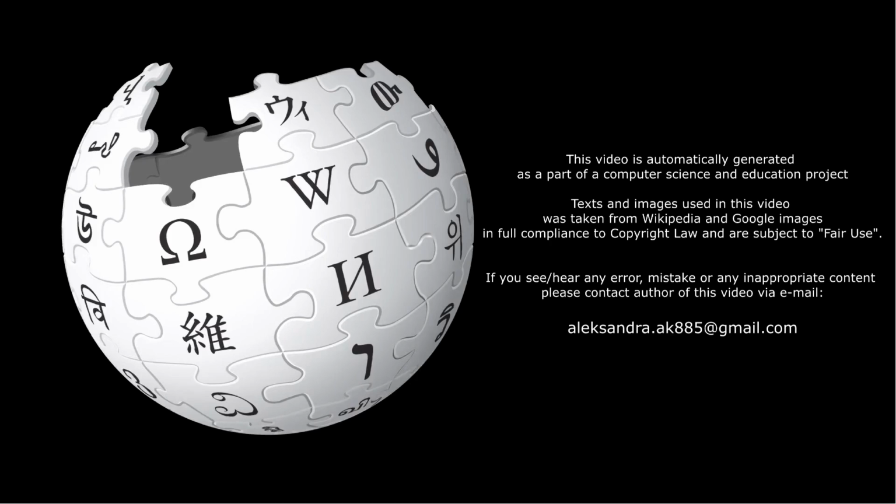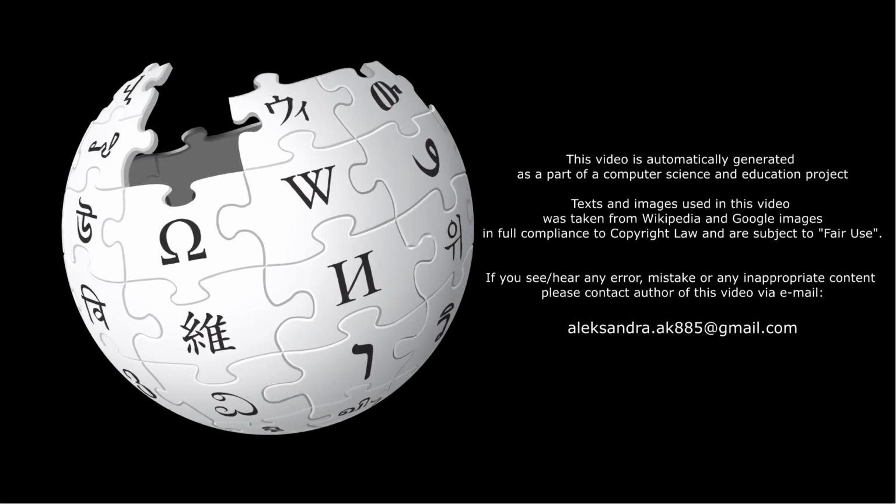The above defect concerns have led to considerations of using a top-coat layer directly on top of the photoresist. This top coat would serve as a barrier for chemical diffusion between the liquid medium and the photoresist. In addition, the interface between the liquid and the top coat would be optimized for watermark reduction. At the same time, defects from top coat use should be avoided, as scanning speeds typically approach 500 mm per second for high-volume manufacturing.